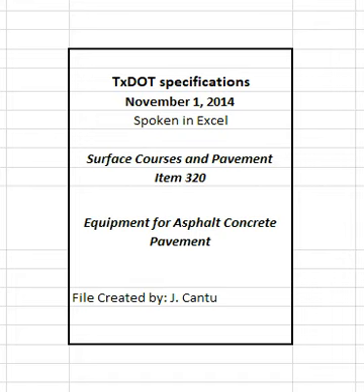2.3.3 Remixing equipment. Provide equipment, when required, that includes a pug mill, variable pitch augers, or variable diameter augers operating under a storage unit with a minimum capacity of 8 tons. 2.3.4 Motor grader. Provide a self-propelled grader, when allowed, with a blade length of at least 12 feet and a wheelbase of at least 16 feet.